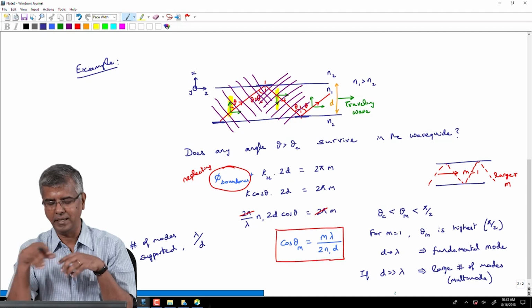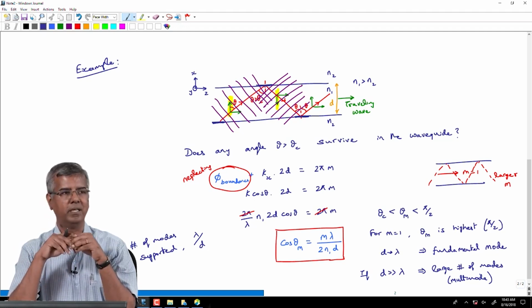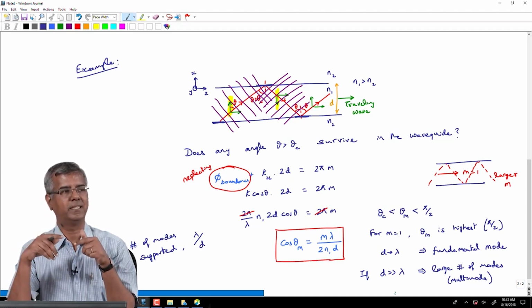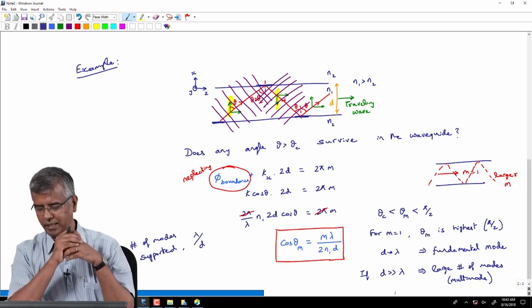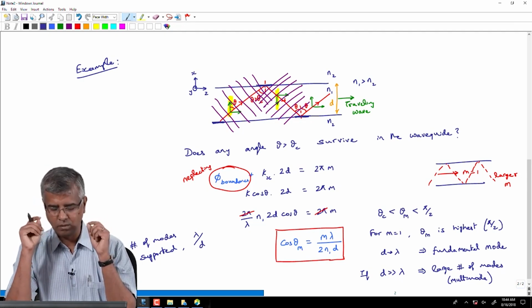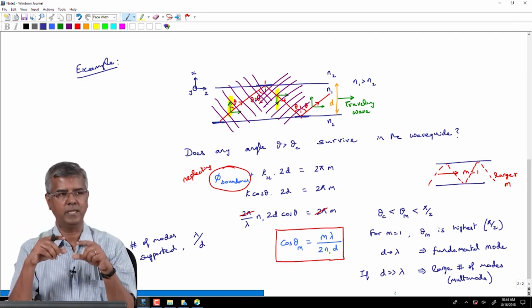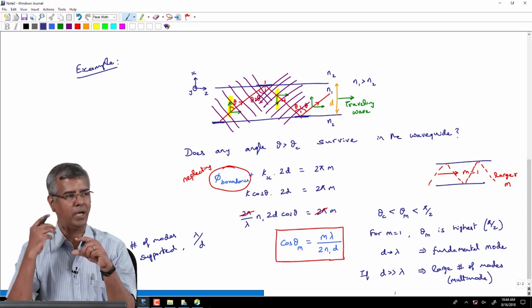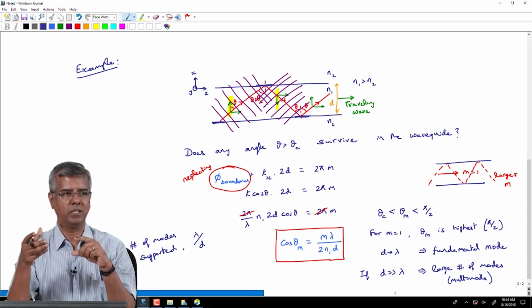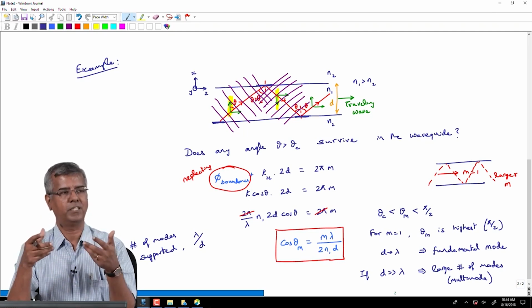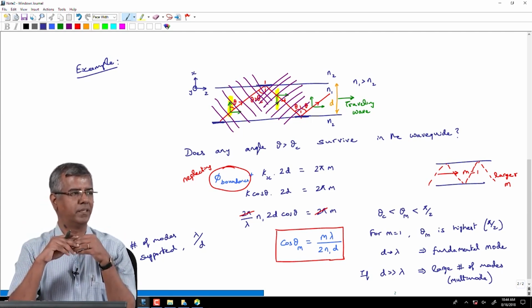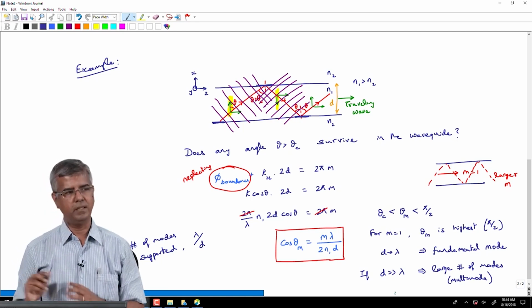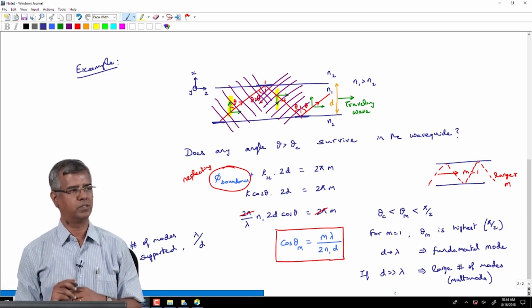But what we are considering here is an optical fiber which is a dielectric cylindrical waveguide, okay. But the principles are the same. Since you have boundaries in the structure, you have this concept of reflection that comes into the picture, and whenever you have reflection, you have interference, and that interference actually gives the concept of modes of the waveguide, okay, right. Higher the order, more steeper the bounce, okay.